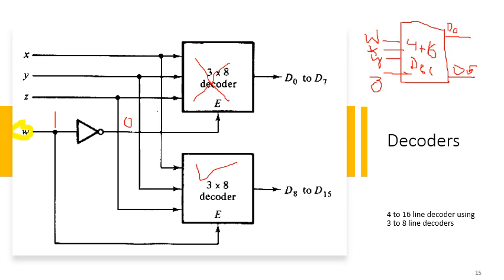And to start with the class, we've discussed a multiplier circuit and we've discussed examples of the multipliers. So the multiplier circuit is a circuit that has the capability to multiply two numbers. The size of the two numbers can be the same or can differ. The resultant product size is always equal to the number of bits of the multiplicand added with the number of bits of the multiplier. So if we assume the multiplicand is of 8 bits and the multiplier is of 4 bits, then the resultant product will be 8 plus 4 equals 12 bits. I hope these topics are now clear.